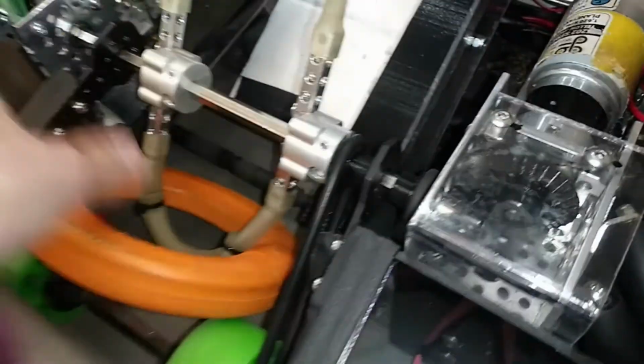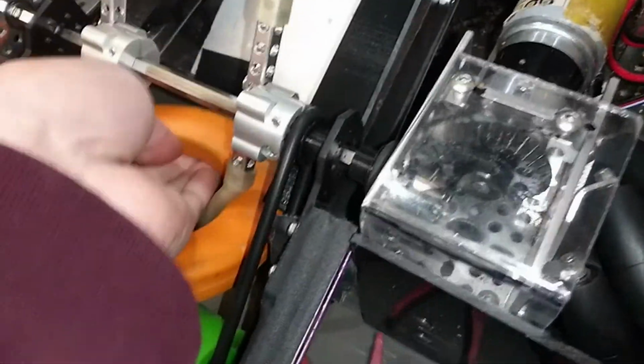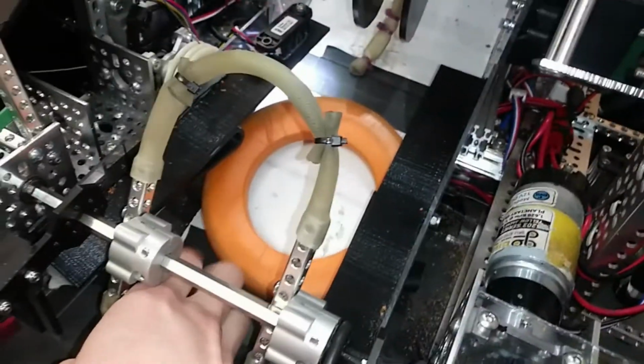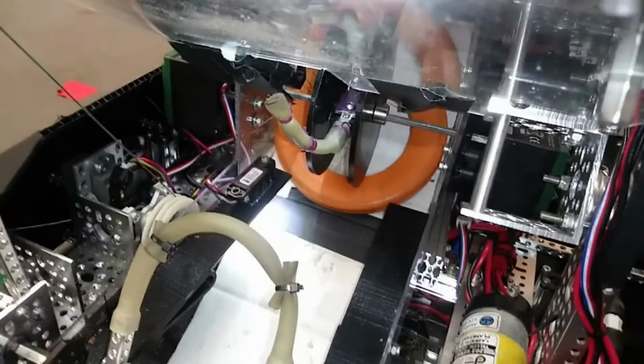The intake also contains 4 distance sensors. These sensors are used to coordinate the intake with the transfer so there is enough space on the robot for rings. When the distance sensor at the bottom of the transfer sees a ring, and all of the sensors at the top see no rings, the transfer allows a ring through. When a ring reaches the top, it turns a green light on.